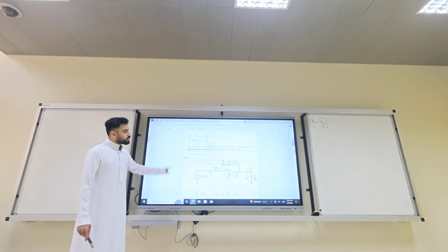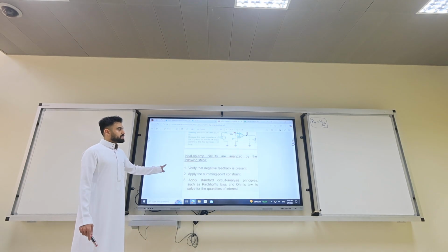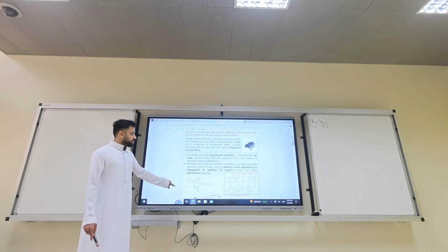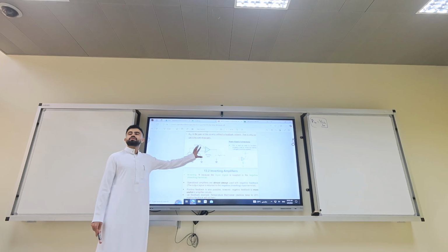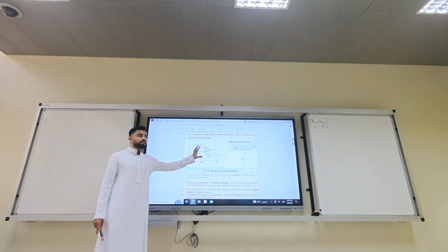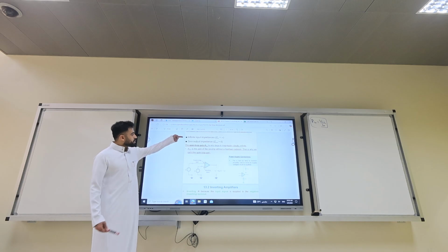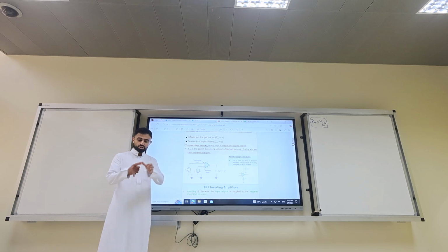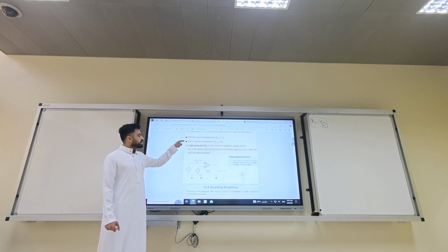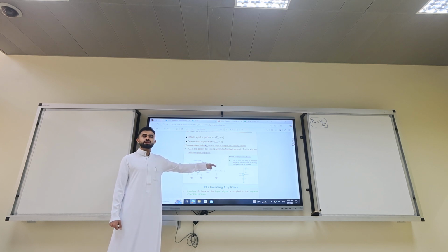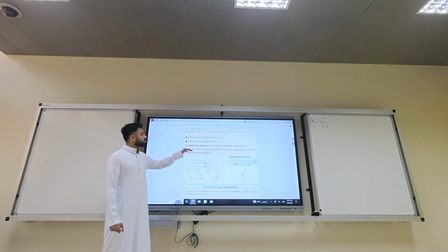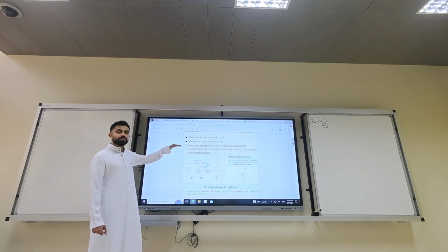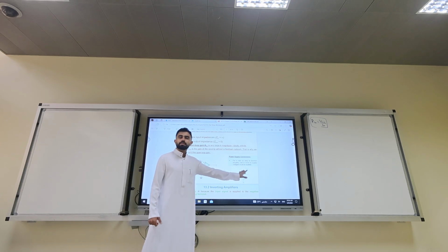Before we begin, I would like to revise some concepts. We started before with the op-amp without any feedback. Without any feedback, we only have these three characteristics. Input impedance is infinity for just the op-amp, the chip by itself, when you connect two inputs. Zero output impedance. Why is it zero? Because it can drive any output, and it has an open loop gain of infinity on paper, a big number in real life, to a point that it shouldn't exceed the supply.